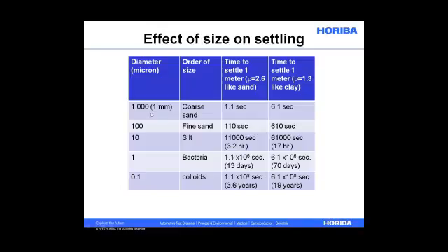So a 1 millimeter particle, which is about as big as sand, is going to settle in about a second to 6 seconds, if you have everything stable in Stokes, and we're going to leave aside whether that's right for such a large particle. But where this is going is you're not really going to worry about that kind of settling process. At 1 to 6 seconds, you're more worried about the stuff settling in your pipes, unless you run your pumps.